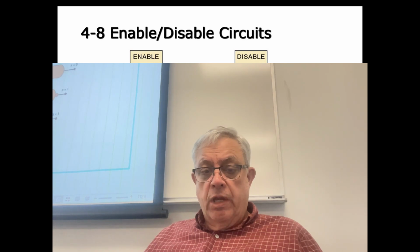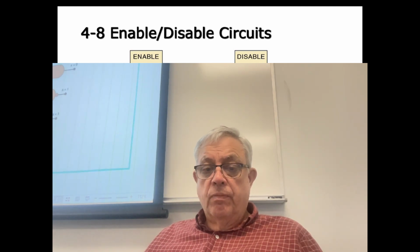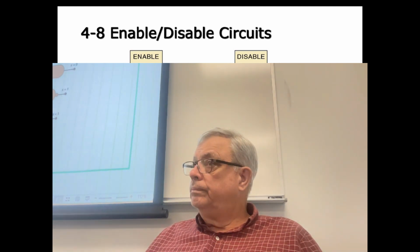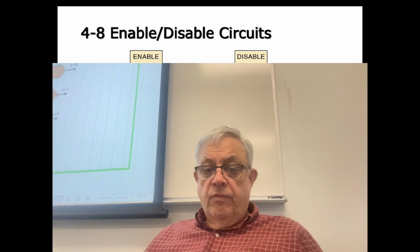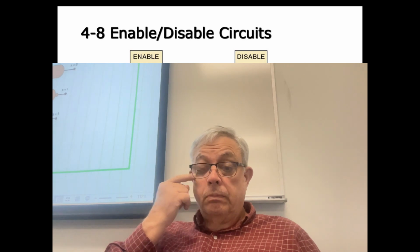With an OR gate, I'm going to put a 0 here, and whatever's on A goes through. If I put a 1 here, I'm going to get a 1 out. And finally, the opposite. If I put a 0 here, that's going to put a 1 out. If I put a 1 here, then whatever's on B is going to come through, but it'll be inverted.